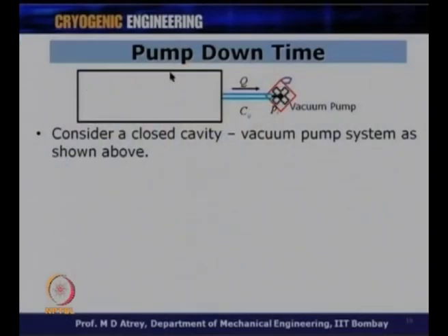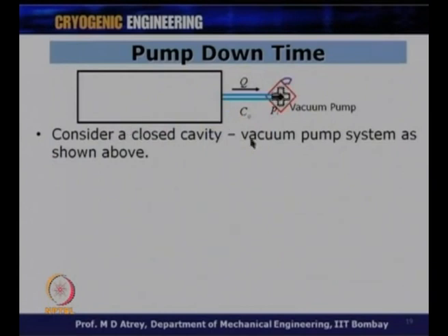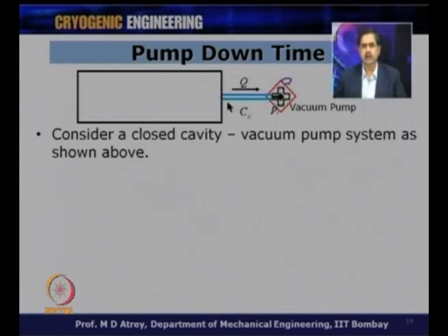Now let us understand how to derive an expression for calculating pump down time. Let us see this system. Consider the closed cavity as shown here with a vacuum pump system: a closed cavity connected to a vacuum pump through a given conductance.